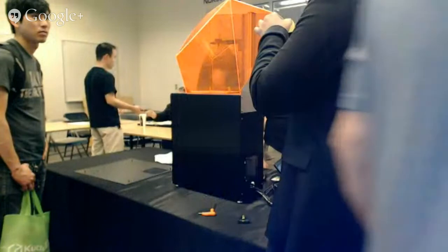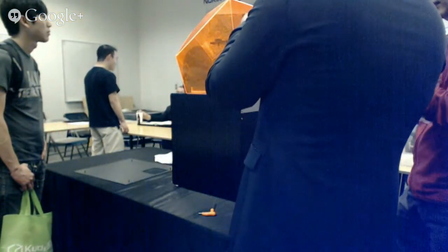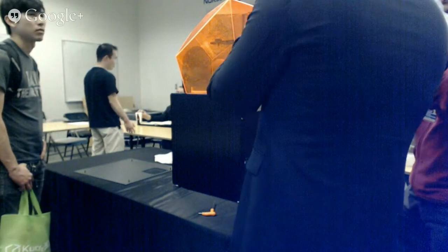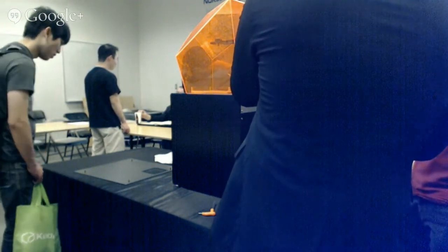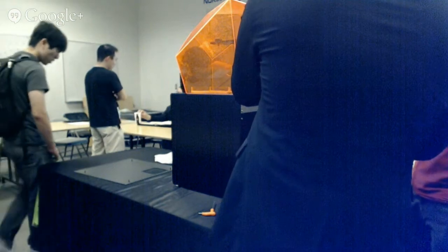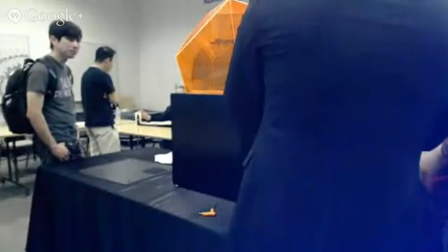They polymerize completely beyond the layer. The resin acts as a light pipe, right? Even if I have a lot of pigments in it, it'll still act to carry light across, and that'll help the layers, especially as you build more layers on top. The layers adhere together better. So the internal layers, because a lot of light has been carried into it from subsequent layers. Yeah, this is pretty strong.